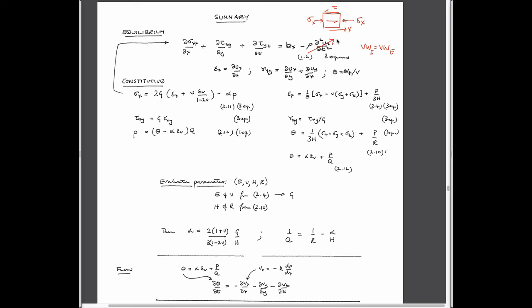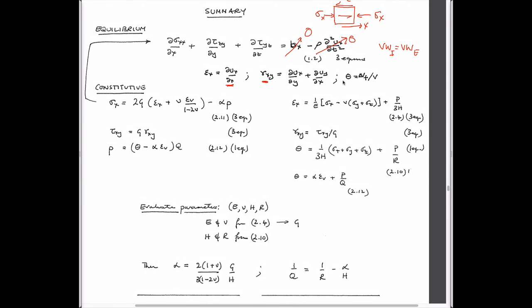The inertial term we don't care about. The body force term we're not going to care about either. Someone asked earlier about that. We know that we can define strains in terms of this. Normal strains are displacement gradients. We know that we can define shear strains in this way in terms of displacement gradients. And we can also define fluid strains as a function of the volume: this is a volume of fluid, change in volume of fluid over the total volume. So just the same as the strain is. So this is delta VF. You can't see it very well.